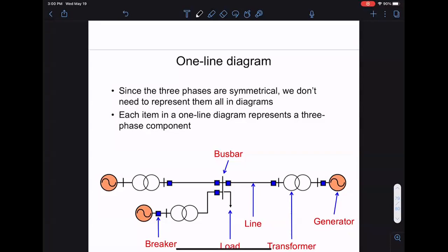to make sure they're balanced. And one interesting fact is that for a lot of distribution systems, we actually don't know which house is on which phase. Right? So if you go to City Light, they may not be able to tell you whether your house is on phase A, B, or C. Sometimes we don't know. This is actually a challenge as more things like EVs come to the grid. We want to balance the load, because the transmission network wants a balanced load, but sometimes we don't even know which phase you're on. So fine-grained management can be difficult.